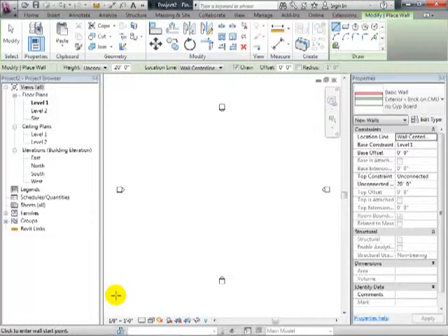So let's go ahead and close it. For that wood veneer, we need to put in something like half an inch, and a quick way to do that is to just say 0.5. That's all it is. It needs some thickness. The only thing that can be 0 is what they consider a membrane.